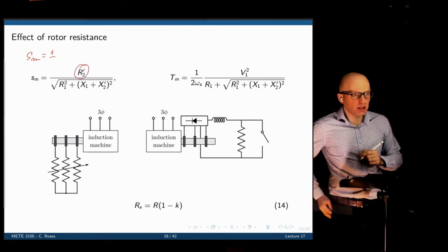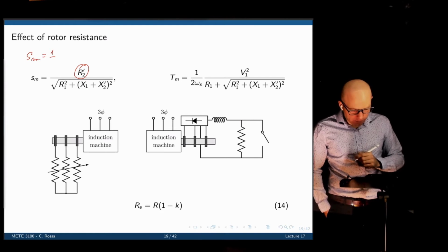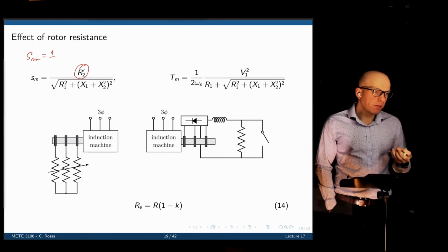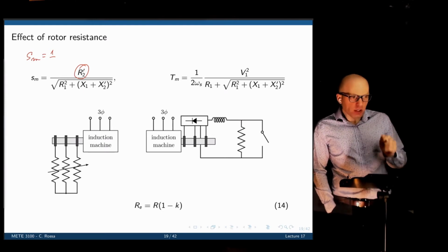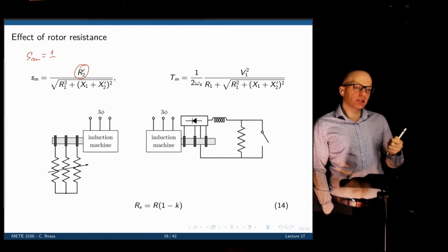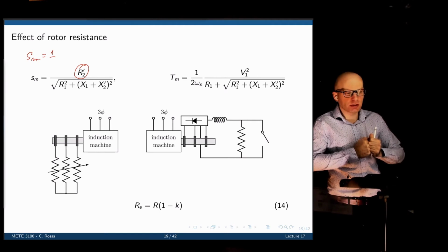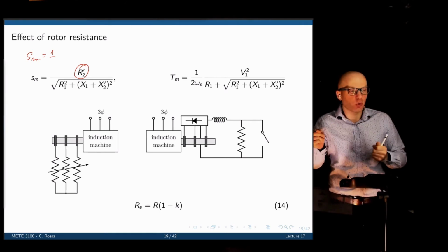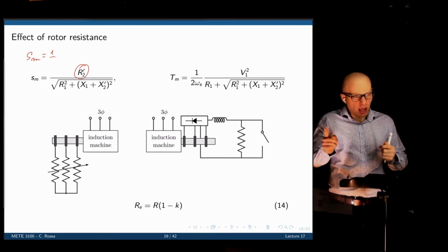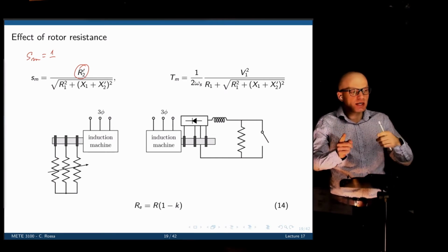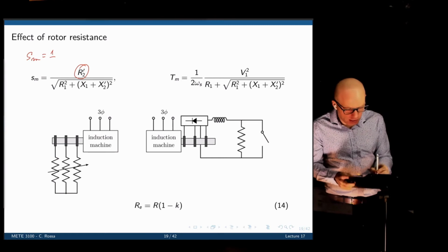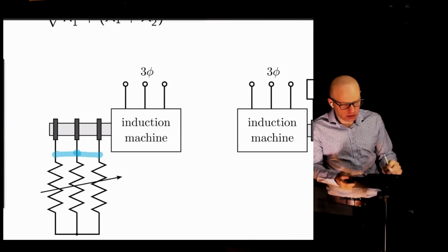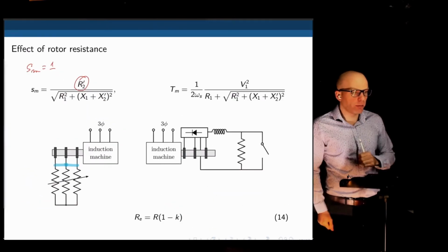So here is where the slip rings will come into play. We can attach each of them to a resistance, and you can increase that resistance in the beginning. When the rotor starts, we attach the rings to this resistance. So now R2 increases, and the point of maximum torque shifts towards this slip of 1. And once the rotor starts to rotate, we turn off the resistance and we just short circuit this winding resistances here so that we go back to a normal operating mode.